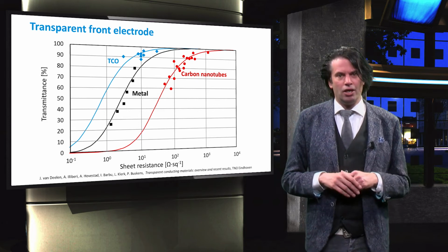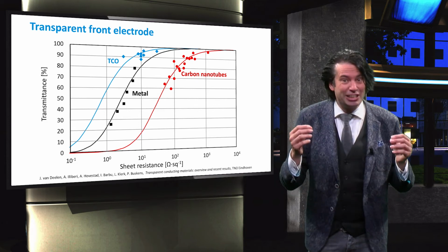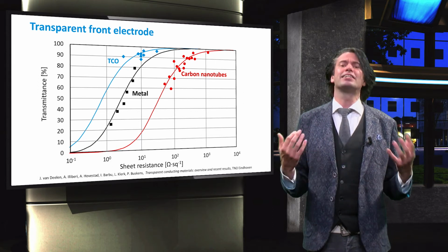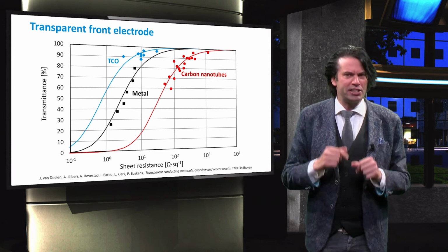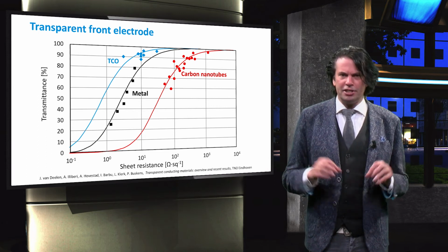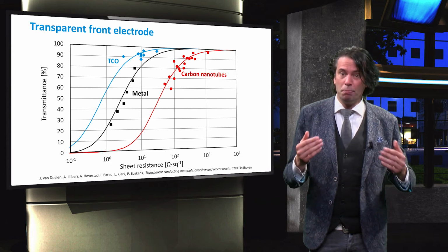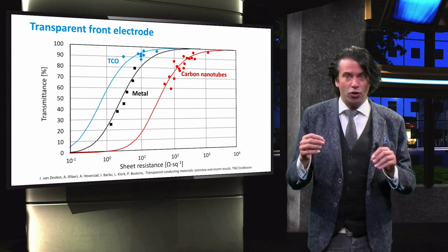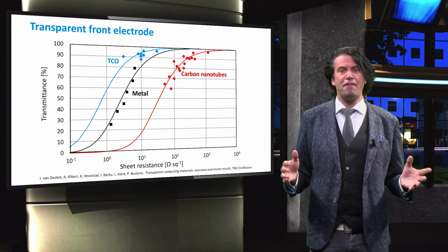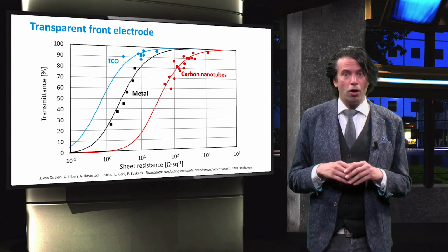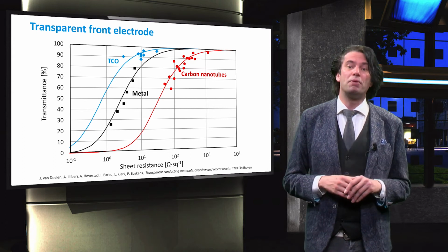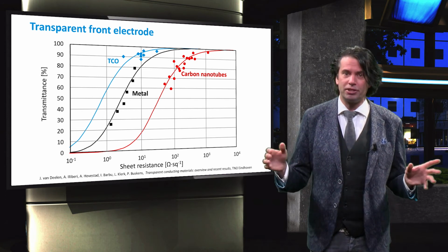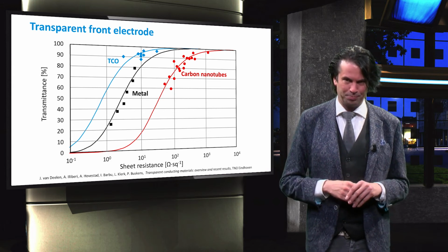A transparent conductive oxide, or TCO, is a metal oxide mixture with a wide band gap. As we can see, the optical and conductive properties can vary quite a bit. These properties depend on the nature, number, and the atomic arrangements of the metal particles in the material and on the presence of defects. The defects can be intrinsically present or purposefully introduced by doping of the material.